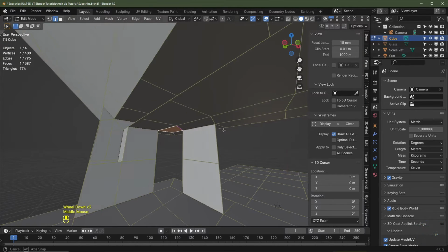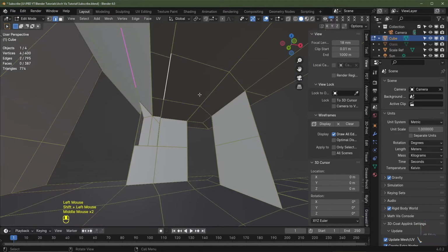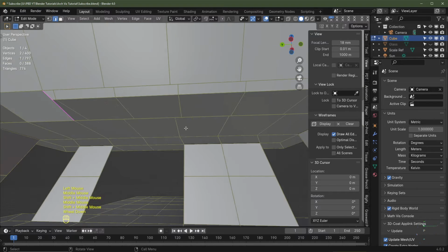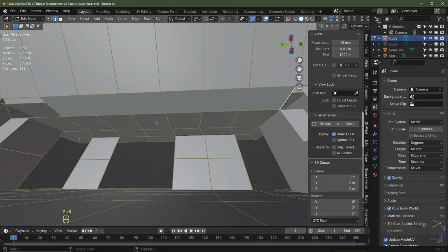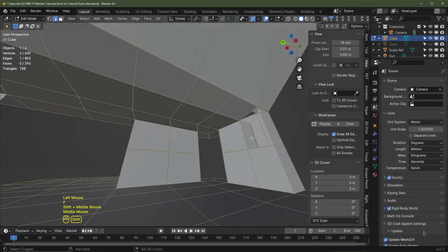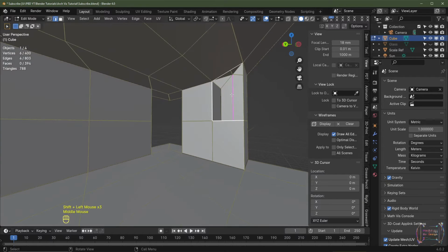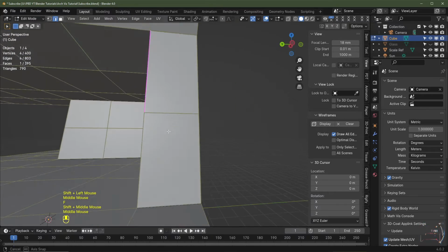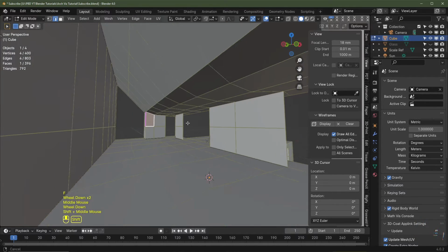So the roof is coming together. So I'll select this one, shift select this one, and we'll fill that. I'll then just select this edge, and hopefully we can do a continuous fill here by hitting F, F, F, and keep repeating that to the end of the line. And we'll do this one, and now we can select this edge loop here. Oh, that's the wrong one selected. Control Z to go back, this edge here, and F to fill that, and one more here.